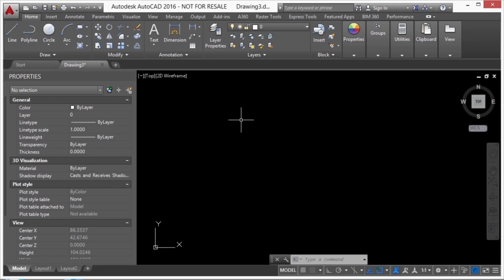Now, you don't always have to use the world coordinate system. You can customize one so it's a little bit different. You might do that because it helps you create a skewed view in your drawing. Or maybe you're trying to lay something out and it's not perfectly horizontal and perpendicular, but on a weird angle, like a 37.5-degree angle. Well, that's kind of hard to do. You can create a user coordinate system, or UCS, that is defined about that specific angle.